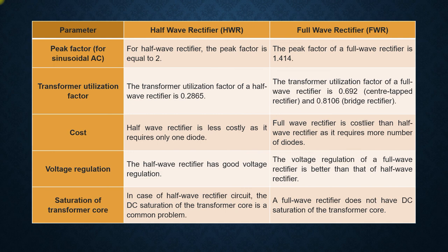Coming to the saturation of the core, in a half wave rectifier circuit, DC saturation of the transformer core is a common problem, and it is somewhat difficult to handle. But a full wave rectifier doesn't have DC saturation of the transformer core at all. This is the advantage.